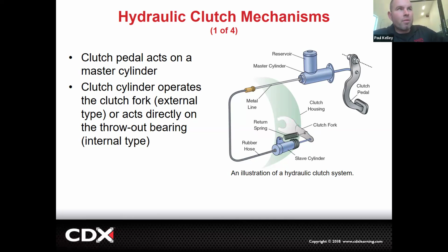Let's just say that firewall was rotted out. 6 inches go to throw this, and let's just go extreme. You lose 3 inches of movement because your whole clutch master cylinder is flexing. You only get a 1/2 inch of stroke. The clutch is still partially engaged. That clutch is going to drag. The clutch is going to drag you into the intersection, grind in reverse, etc.